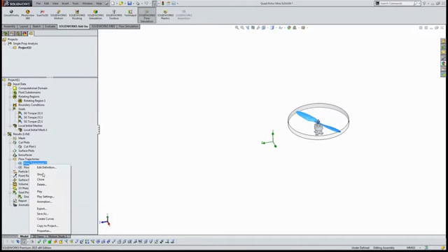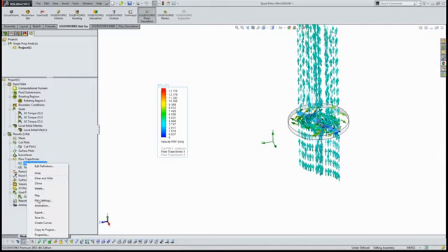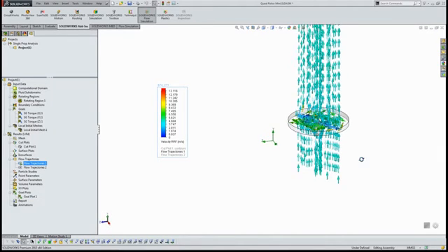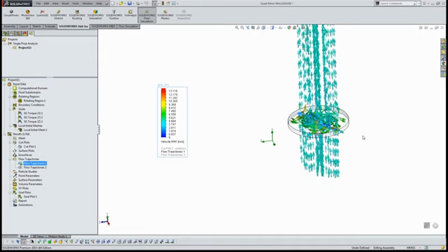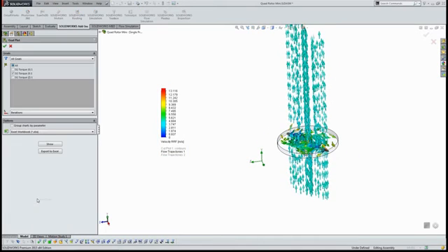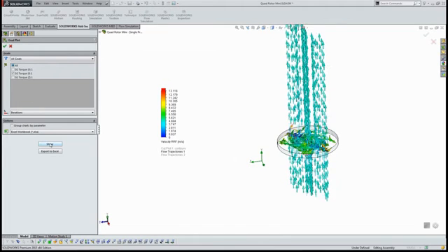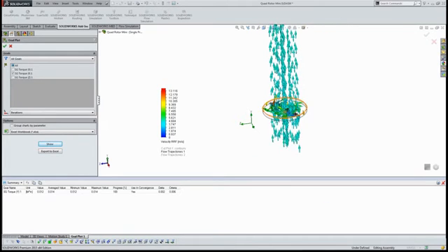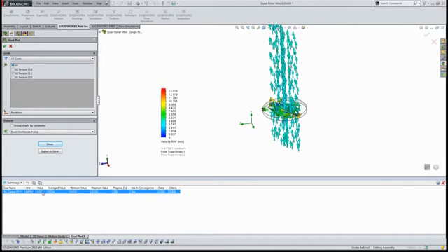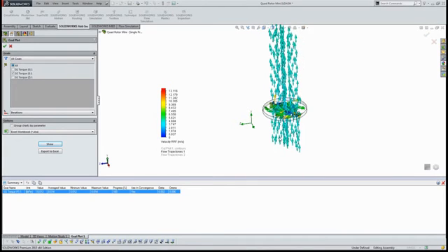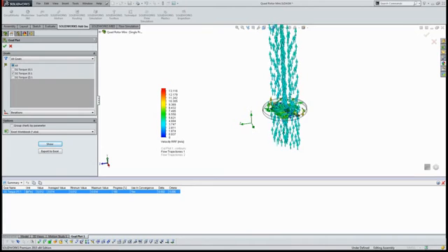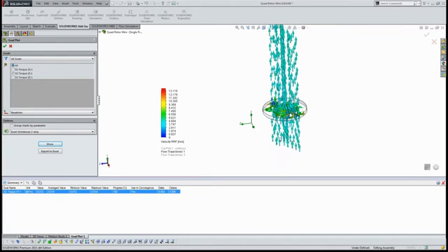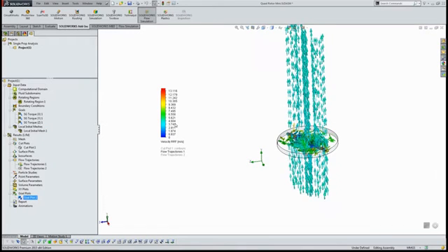And let me just show you guys some of the results here. We can take a look at what exactly the results look like. We can see the flow coming through the propeller, and that's obviously nice. But really what we're probably interested in is, how much torque is that generating? You can see the torque in the Y direction is whatever it is. Don't worry, the number is not as important here, it's just showing the physics. So let's say I'm assuming I want to use a 2-propeller system. Maybe I want to also look at 3 or 4 propellers, or change the geometry of the propellers to try to get some desired torque or thrust. All things that you can do inside a flow simulation.